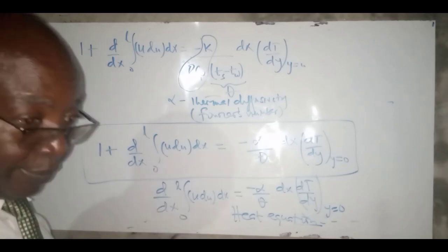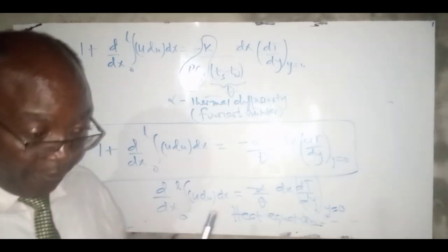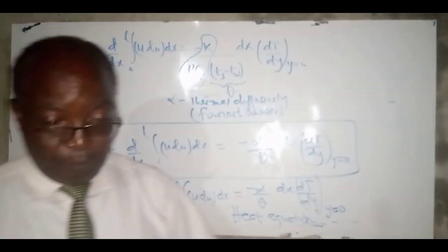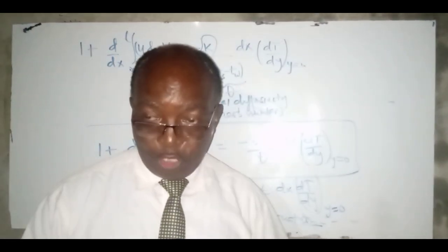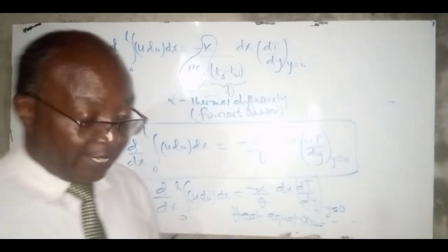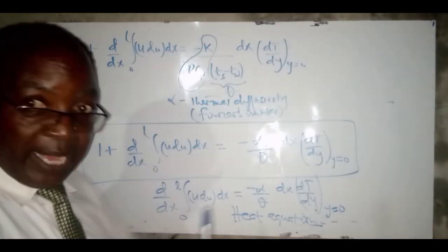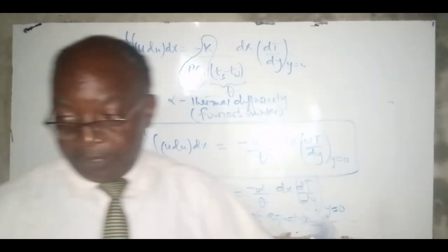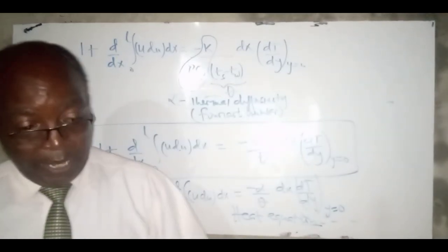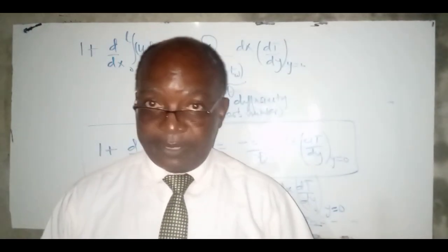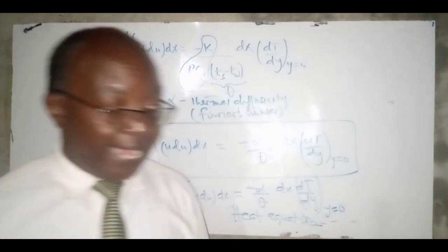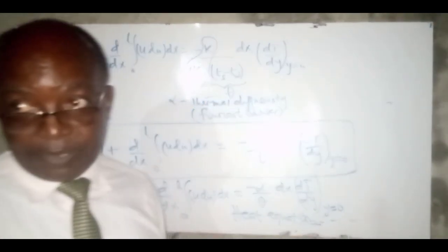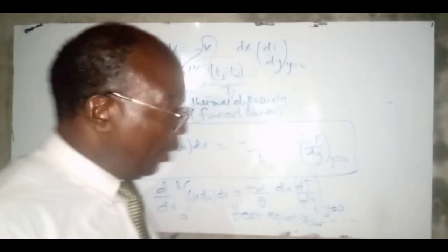You have seen how we have proceeded using the steady state expression, where we have assumed there's no change in datum level, so the potential energy is basically 0. Then the specific enthalpies and kinetic energies expressions are the ones left, and that is equal to the heat transfer to the system, because we assume there's no work done on those masses.